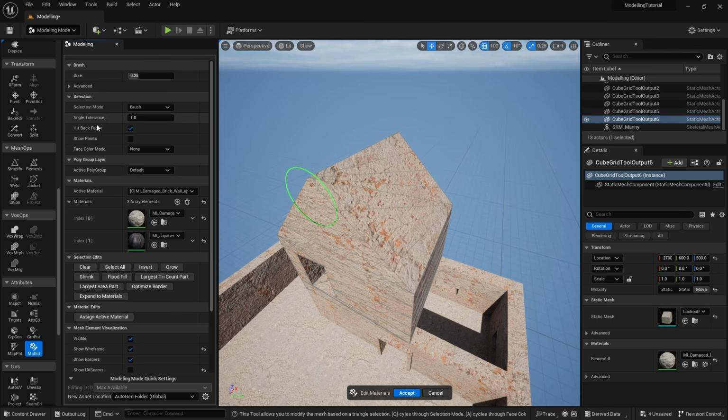Now in the selection mode here, you've got various different options. Now the way that it works, you can see there's lots of triangles here at the moment, and you don't really want to be selecting all of the triangles, but the way that Unreal Engine emulates other content editing tools that are face-based is it creates something called polygroups, and the polygroups are effectively the faces, the planar faces.